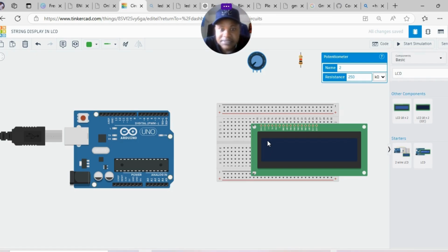And if you operate it under command mode, we simply mean that whatever is sent to the LCD by the Arduino, the LCD will interpret it as instructions, and therefore it will respond or do what those instructions demand. So that is all about our RS, or rather the register select pin.